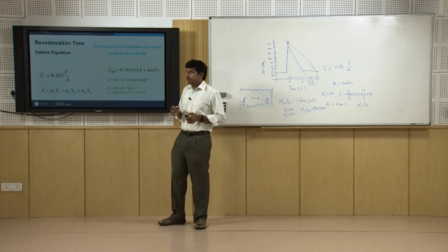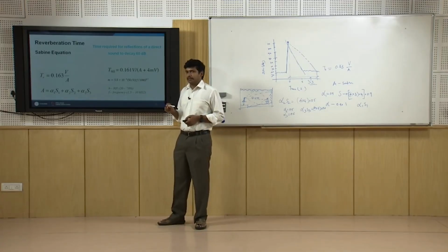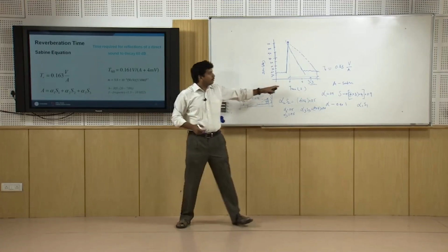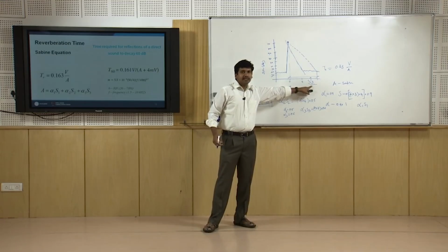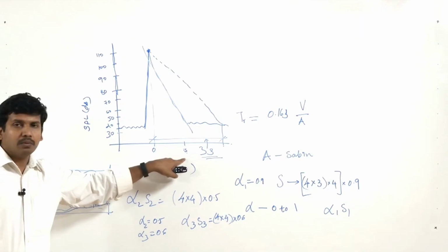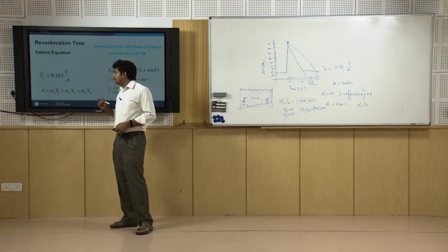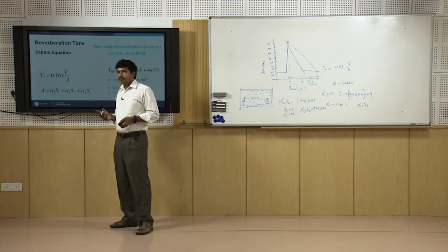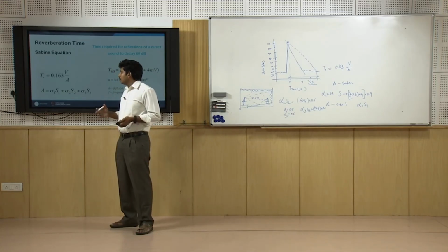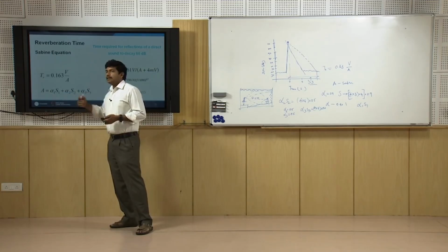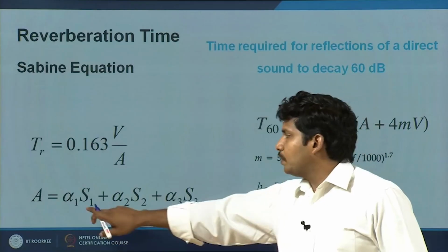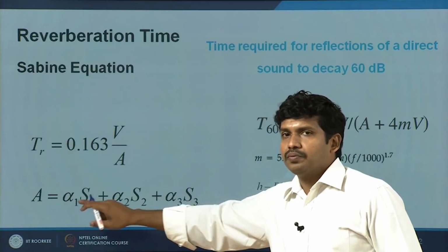So in this context, if you are wanting to reduce the reverberation time, that is where we are talking about, say imagine the original reverberation time was 3 seconds, you want to bring it down to 1 second. There are different methods to do it. The common method which any material seller in the industry would tell you is to go for an increased absorption coefficient.